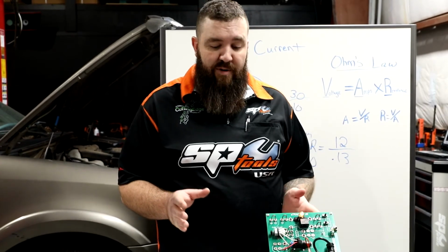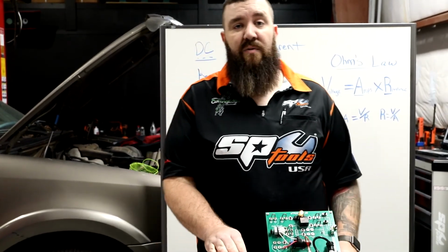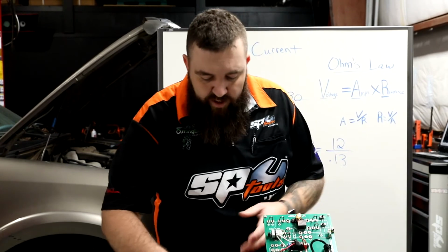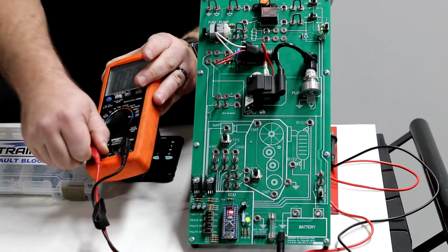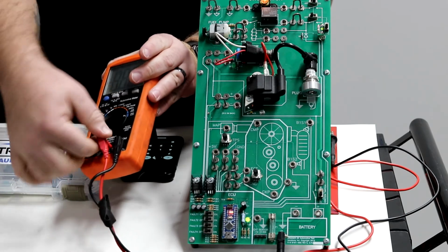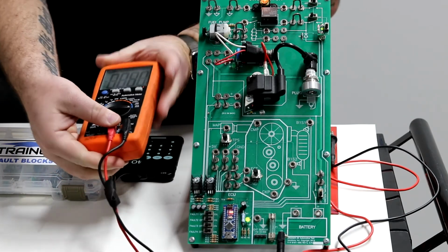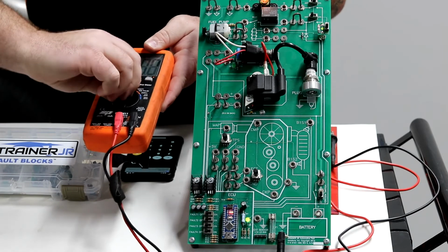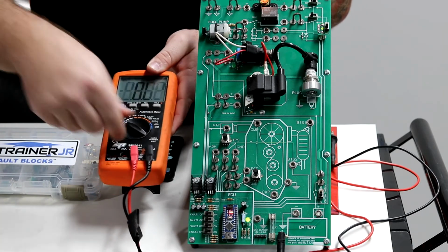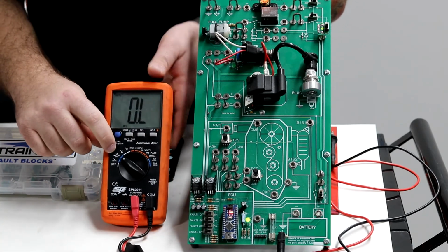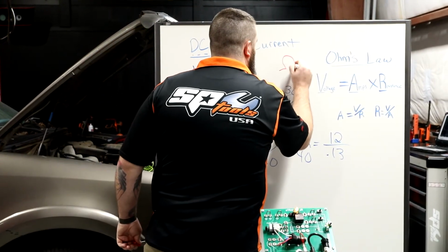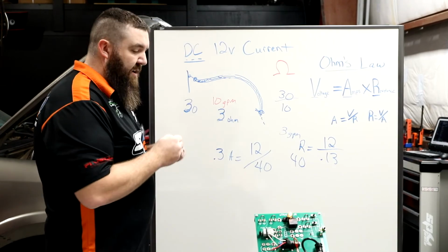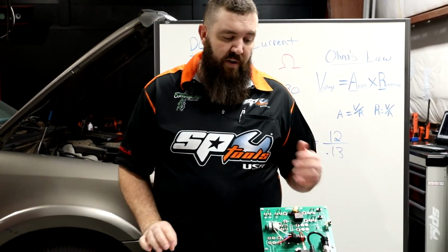Now for the last portion of today's video, I want to be able to show you resistance values with the meter here as well. Now we're going to be putting our meter back into the standard function in the positive port, and then we're going to change our meter over to the ohms or resistance spot. And if you guys don't know what ohms looks like, this little symbol right there, that is ohms or resistance within your meter.